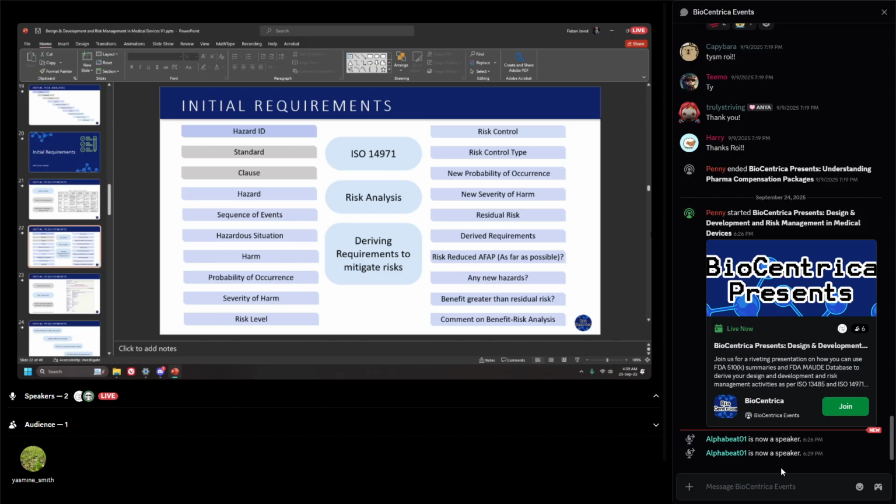An example would be that the exposed surface of a medical device can get too hot because it's a heater. So initially it was getting up to, let's say, 150 degrees Celsius. So that can give you the extreme kind of burn. But the mitigation was that we put a controller into it. And then we also supplied it power in such a way that the maximum that it can go is, let's say, 50 degrees Celsius, right?